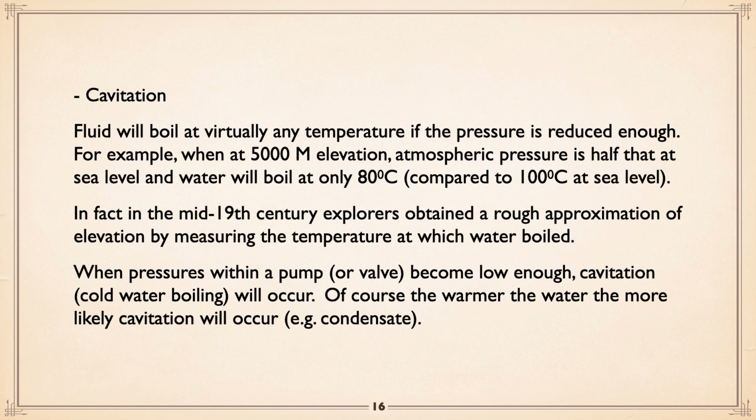Now, when pressures get low enough in a pump or valve with flow rate, you get cold water boiling, which is cavitation. And of course, the warmer the water, the earlier that will occur. For example, condensate, which is steam from a boiler or whatever: as steam is condensed, that liquid condensate is very hot and it doesn't take much drop in pressure to get it to boil. Now,